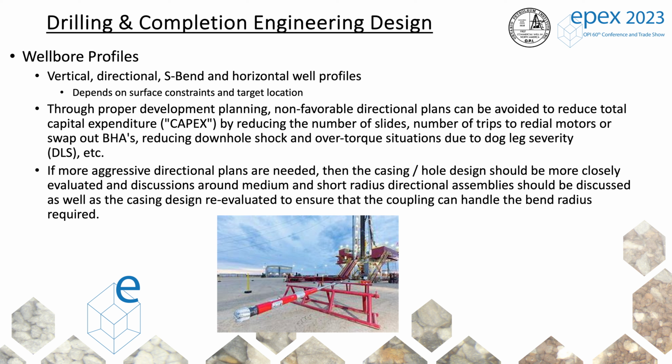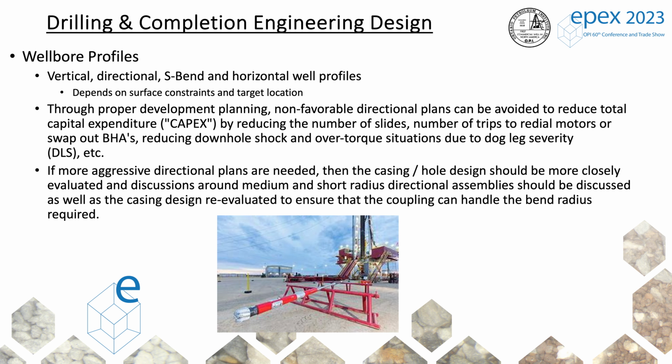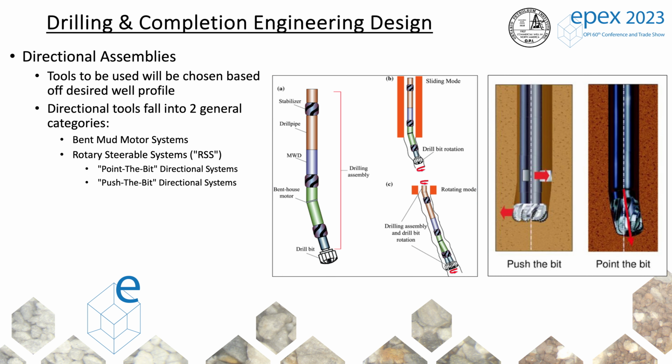Wellbore profiles: for the salt wells, we've seen anything from vertical to deviated wells, S-bend wells, horizontal profiles. It's obviously going to depend on the surface and downhole constraints as discussed by Colton earlier. I wasn't going to get too much into the torque and drag, but we're always running our torque and drag models, making sure that we can get that casing to bottom.